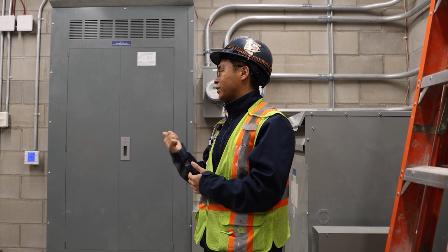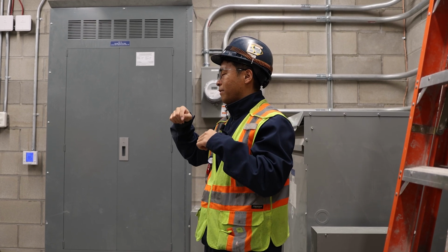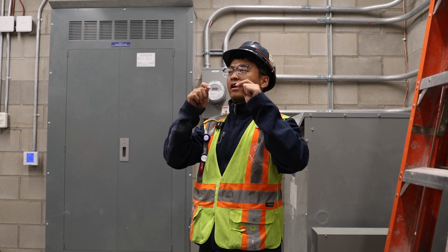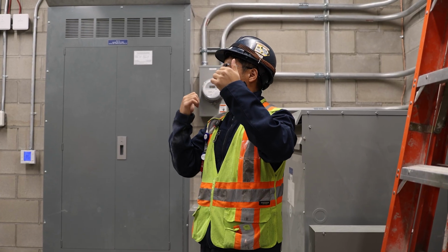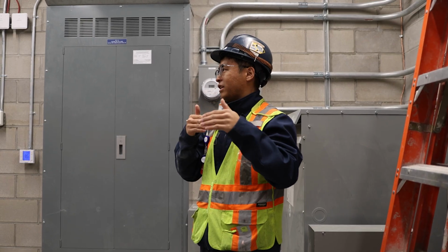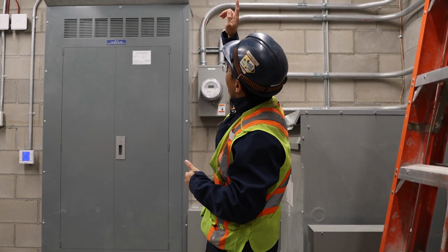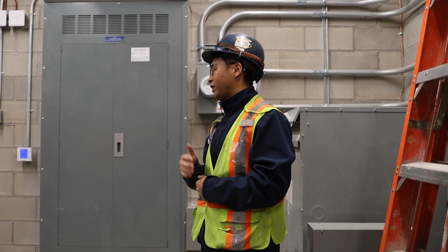And in the summertime, it reverts the other way. The heat pump does the cooling to the room, and the heat pump condensing side will be hot, and it requires cooling. When it requires cooling, the heating pipe isolation valve will be closed. The cooling isolation valve will open, and then the pump will be running. The 3-way valve will modulate to maintain the loop temperature at 30 degrees.